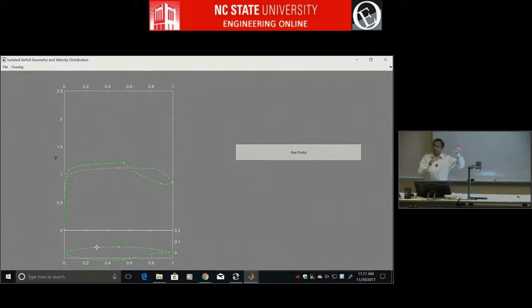Maybe you do the very first one, like let's say you want to move everything towards the leading edge, right? You take the very first one near the leading edge and move that to some place. Put that Newton iteration first, then that will converge. Then you move the next one, because that's already moved, it's created some space. If you put them in order, one will move, then the other one will move, and then everything will move. It might take a little bit of time to get that working if you have a bunch of segments. But I've done it. Once you think through that and do it, it's pretty useful.